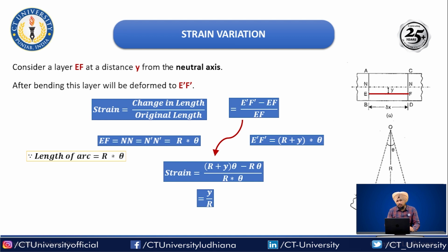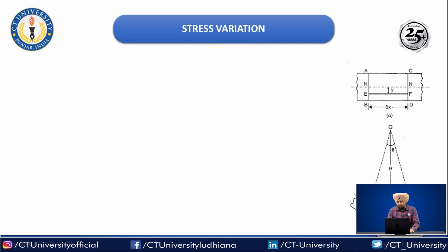So what is this equation denoting? That the strain in any layer can be calculated, and it directly depends upon the distance of that layer, that is y divided by radius of curvature. It is directly proportional to the distance from the neutral axis.